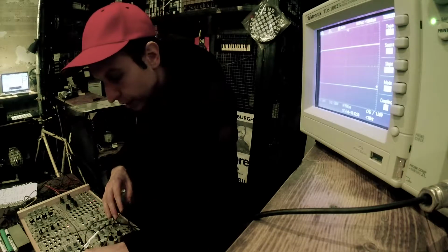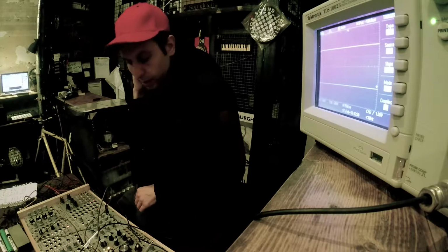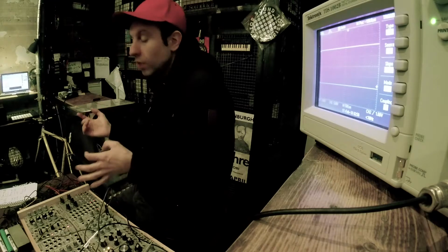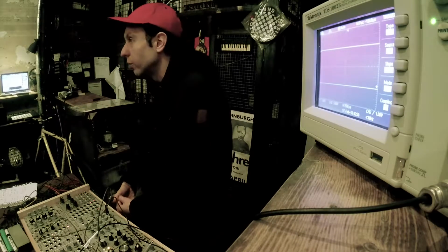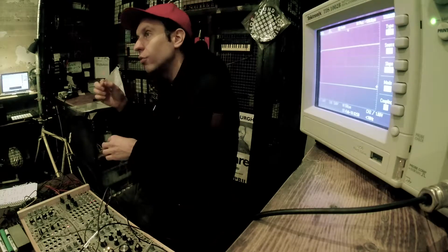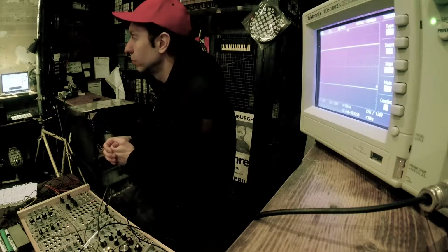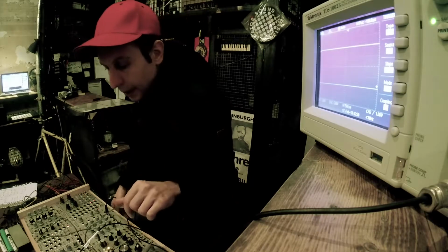It's worth saying that in digital systems, white noise is generated by synthesizing a uniform distribution random value for each digital sample, and that is white noise. Brown noise you can synthesize essentially by having a random process which steps away from the previous sample value, which has to do with Brownian motion. I don't know if you know about this.